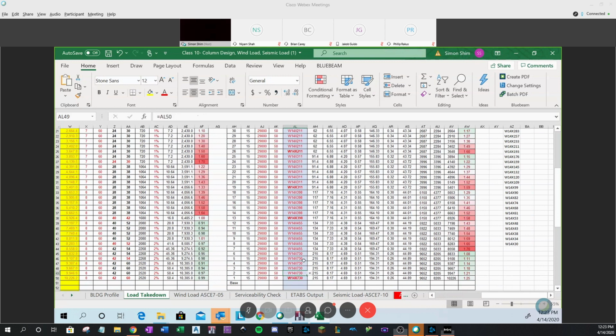Use a built-up section, but similarly, using those design actual loads, you could just choose the members. You have all the AISC rolled sections. You choose the members, and then you check the design load versus capacity, and you could size the column.